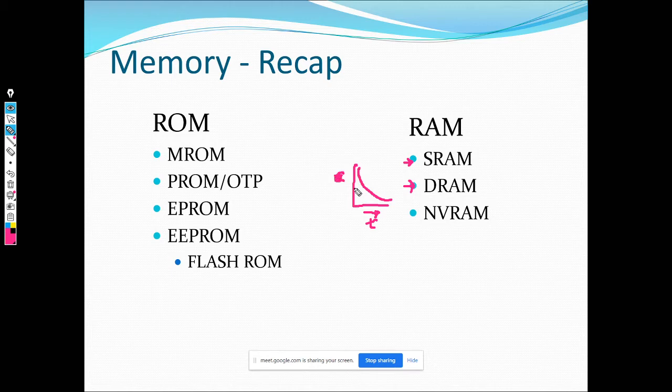Sorry. So your charge is going to come down. Okay, so exponentially it's going to decay. So what you have to do is pump the charge beyond a certain time. Let us say you call this a 1, and you call this a 0, right? Then your 1 will slowly become 0. So you will know the time, right? Before this time, you will have to keep refreshing it, so that it maintains the state 1 if 1 is programmed. So that's your DRAM.